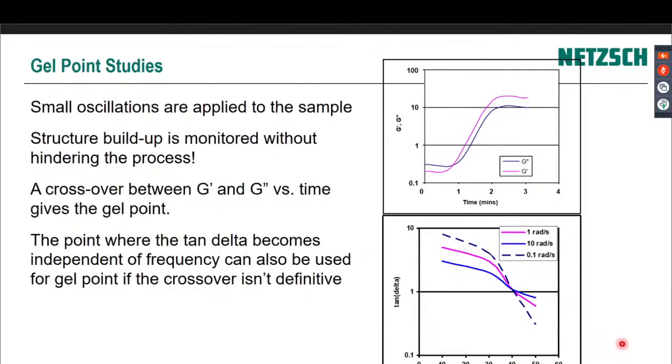So to do a gel point test, we're going to oscillate within the linear region, and we can put our sample in. Maybe we cool it down over time and see what happens, or maybe we'll just leave it isothermally while it's oscillating, and we can watch if it just gels up with time. So you mix your samples together, whatever you expect to gel is going to gel,